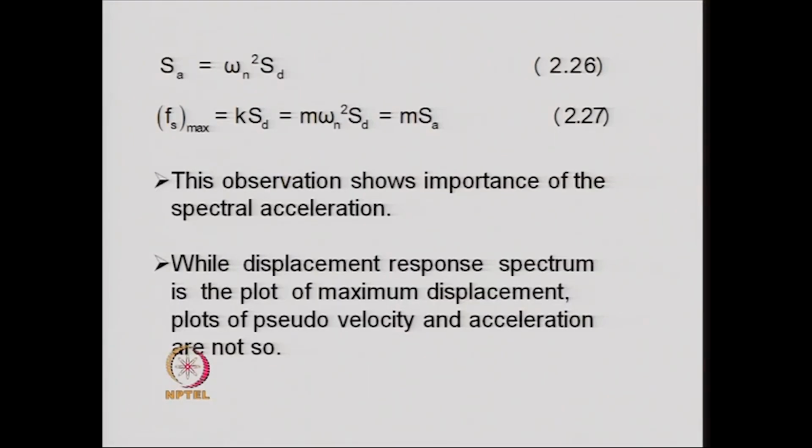Now, this observation shows the importance of the spectral acceleration. While the displacement response spectrum is the plot of maximum displacement, the plots of pseudo velocity and acceleration spectrums are not so. That is, the pseudo velocity is not equal to the maximum velocity. The pseudo acceleration or spectral acceleration is also not the maximum relative acceleration.